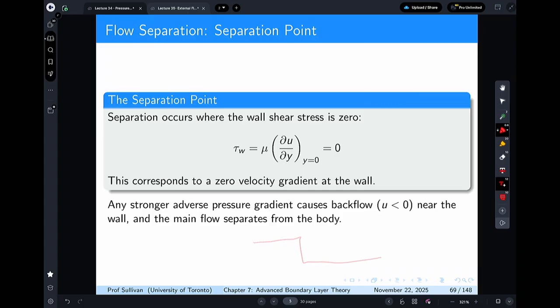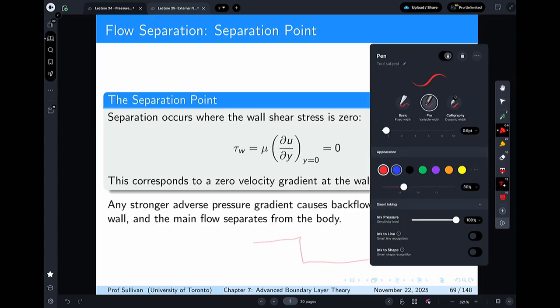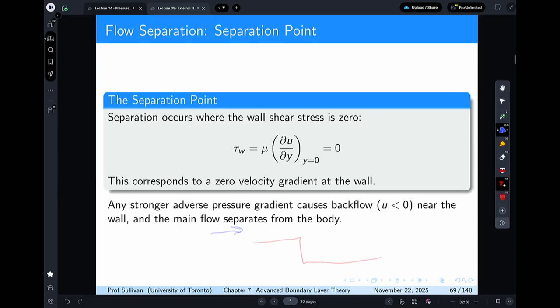So a backward-facing step is just this. You have flow coming in left to right. Flow goes over, and you have a recirculation that will appear. That recirculation is going to be constant, but there's going to be a point where shear at the wall is equal to 0, and that indicates the difference between when flow is moving forward and when flow is moving backwards.